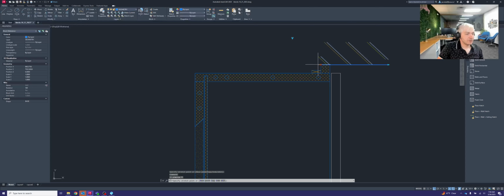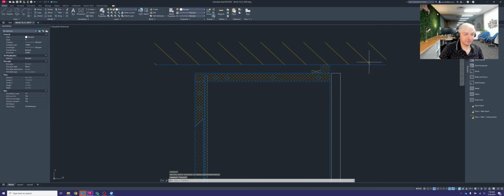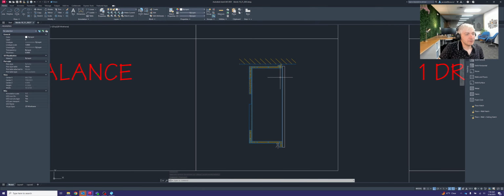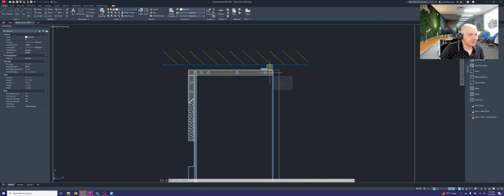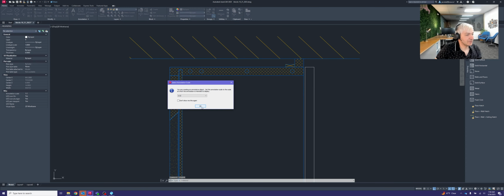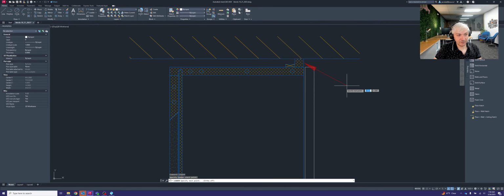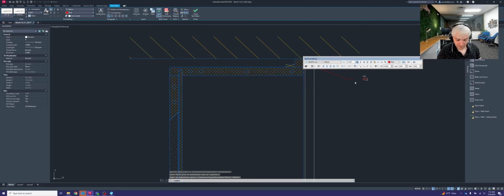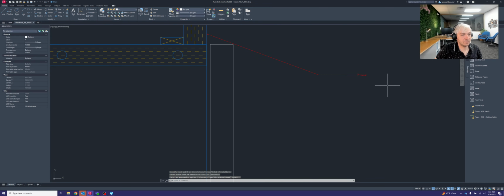Okay. So let's say your cabinet was constructed in a way where there was either a soffit or a ceiling right above that cabinet. Now, if that does happen, it is going to be really important to remember that we do need to place a reveal in between the ceiling and the top of your cabinet. That reveal is typically 3/4 of an inch.